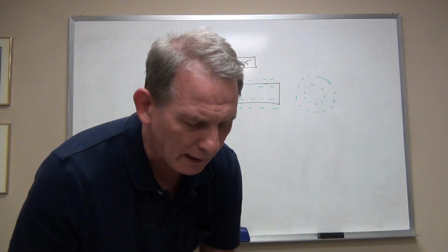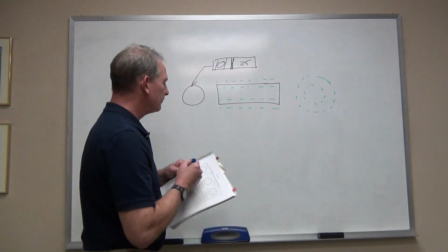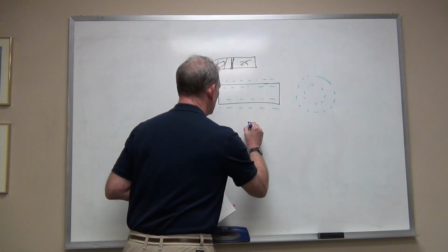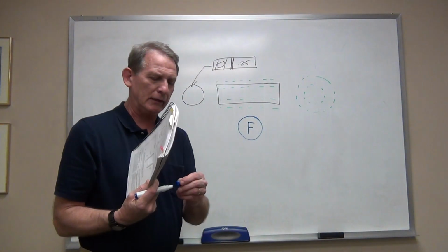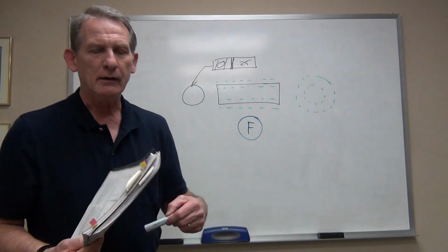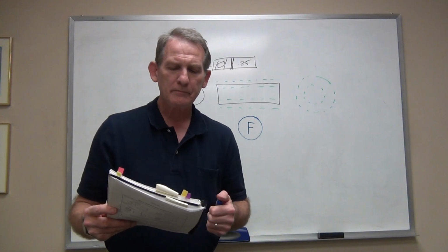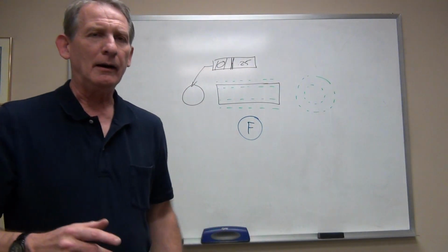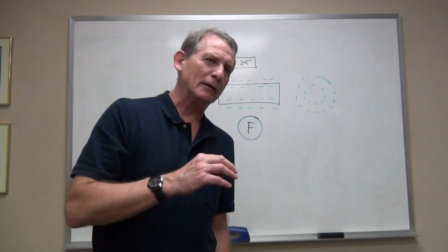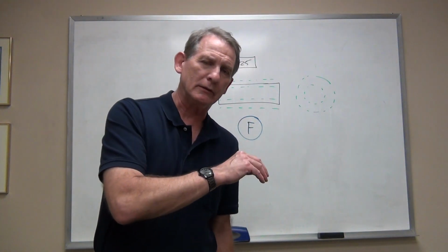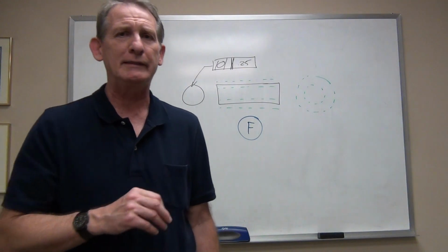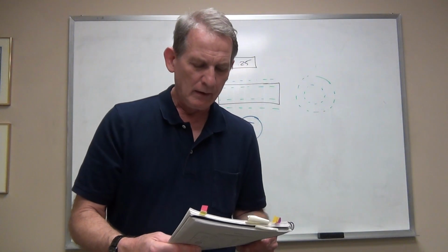I do want to point out one other symbol. If you look in the feature control frame in both of these examples here, you'll see that there is an F in a circle. Even though it looks like a material condition modifier, it really isn't. If you look at your list of tables, you'll see that it is a free state symbol.